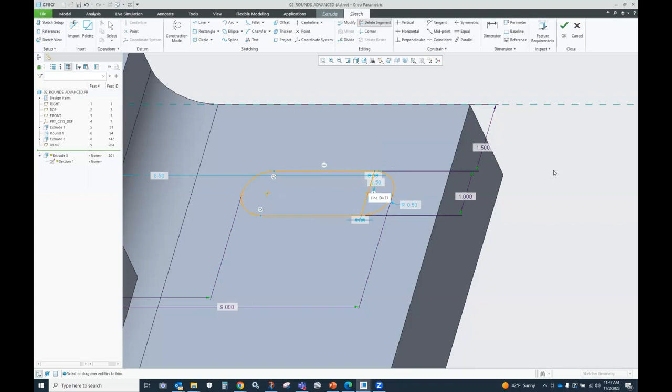Now, watch what I'm going to do here. I created my new geometry, and rather than deleting this, I want to remap my IDs. Oh, now that's arc 25, that's one, and that's 28, 25 and 28, right? Now, what I'm going to do is pick on this 25 and replace it with 28. It's giving me a warning saying that the dimension scheme can't be recreated, so I'm fine with that. But watch what happens there now.